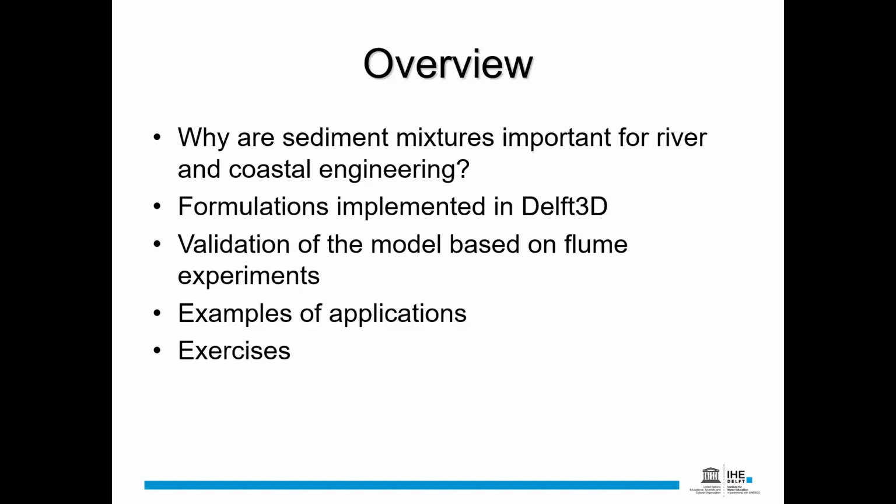First, I will just briefly explain why sediment mixtures are important for river and coastal engineering. Then I'll explain the formulation implemented in Delft3D and how this formulation is validated using flumes and experiments, and maybe one example of application, and we will do some exercises together.